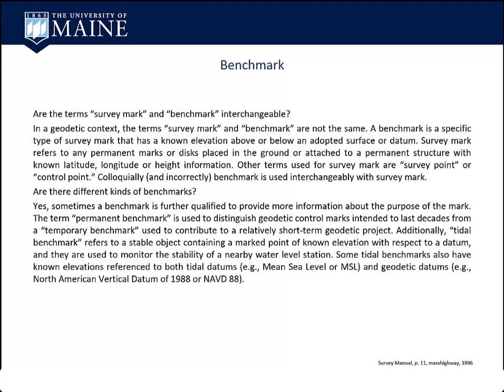So tidal benchmarks are a little different. They reference a tidal datum: mean sea level, mean lower low water, mean higher high water. There's a whole gang of them. It's kind of a specialized thing. And there's a relation to the geodetic datums, because GPS is not going to give you tidal datum.